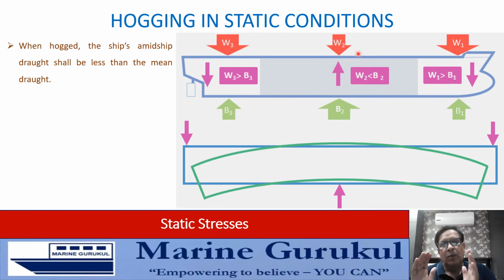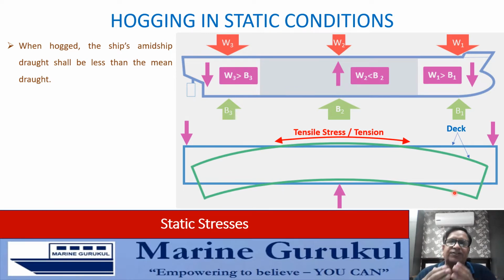Now, when the ship is hogged, the upper parts of the ship, that is the deck region, which you can see here in this diagram, is getting stretched and is under tension. The upper part experiences tensile stress.